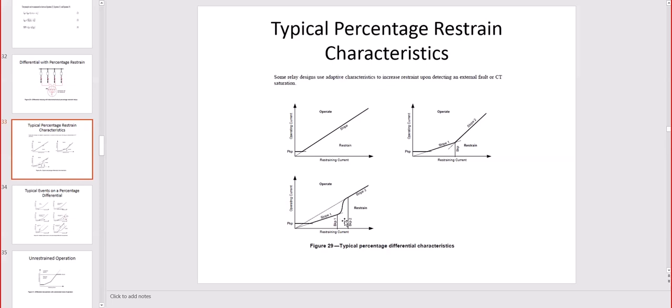And another example for a digital relay is actually an adaptive slope that you can see on the bottom, with the operating point above the line and restraint where it's not going to operate under. So under, it may be a fault outside the 87, but it's not going to trip the 87. So the system knows that some other stuff happened in the vicinity of the equipment and the device.